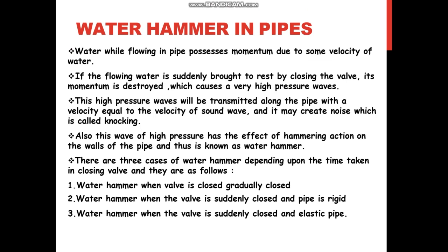Means when the water is flowing through the pipe, if suddenly the valve is closed, because of the destruction of the momentum of water, very high pressure waves are created in the pipe, which travel along the length of the pipe with the velocity of the sound wave, and hence produce a noise, and that noise is called knocking. This high pressure wave also has a hammering action on the walls of the pipe, and hence it is called water hammer.